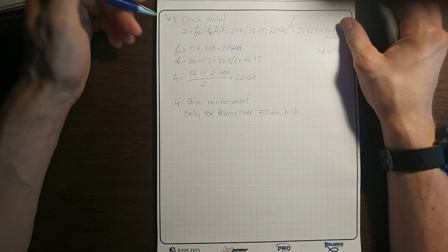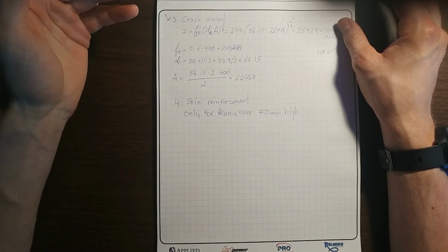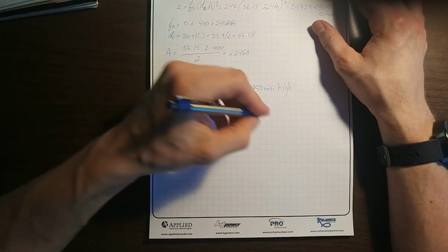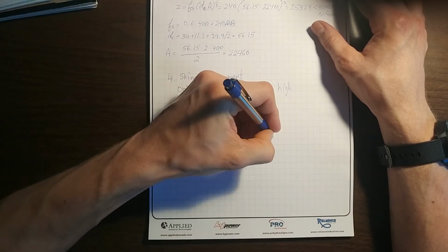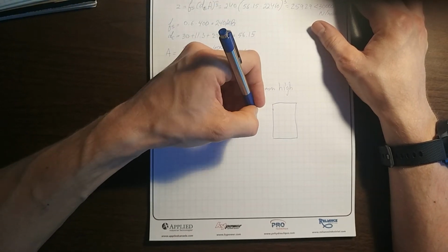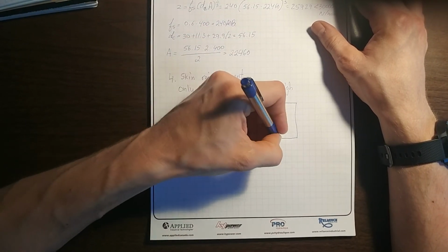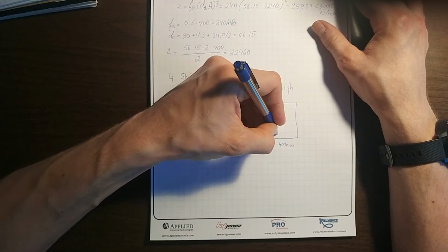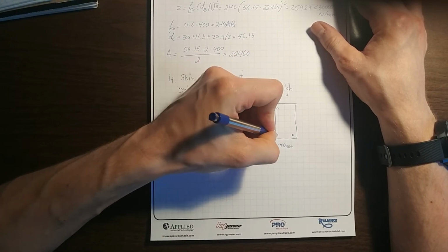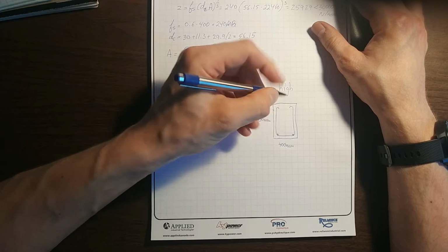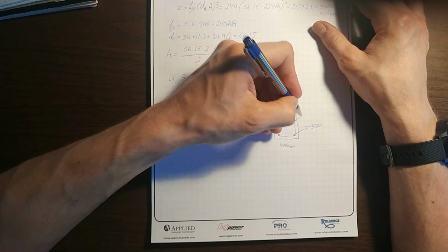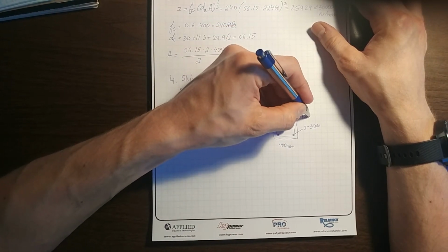Okay, so this is how you design the beam for the bending moment, for singly reinforced, for the tension reinforcement. And we can also draw this beam just to show how it's going to look. So this is going to be our 500 millimeters, so 400 millimeters. We got 2 bars, the stirrups. So these 2 bars are going to be 2 30M bars, and these stirrups are going to be 10M.